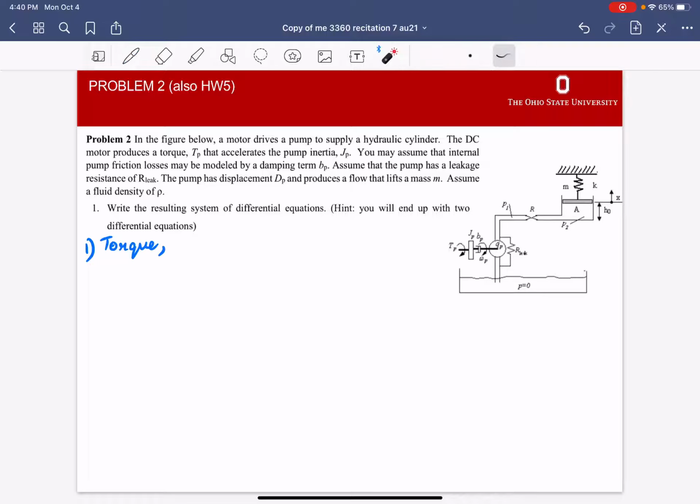What I'm doing right now is focusing on this small fraction over here, and that's looking into the input power of the system. This is where I'm looking at my torque balance like we had done last week. So that would be the inertial moment, Jp, times the angular acceleration, which is equal to Tp. Now there was some confusion. Here Tp is your input torque. Generally what we took Tp as was the torque going directly to the pump, but here it's the original input torque.